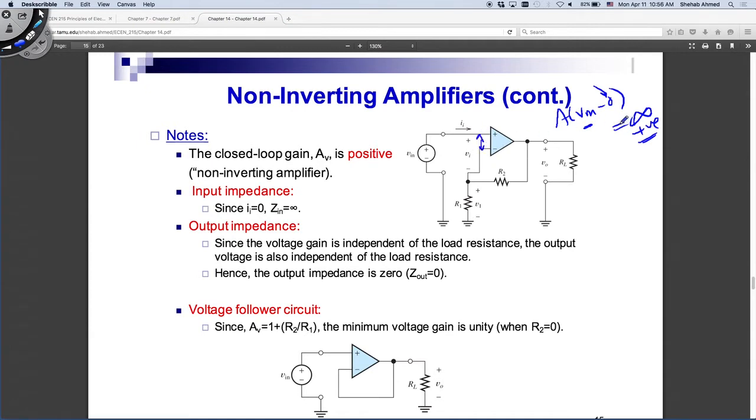If I bring back a negative number, what's going to happen in this case? If I put the resistor here instead of here, what will happen? I'm bringing back a voltage to the negative terminal. The output will be A V input times another circuit in parallel with this. It's a voltage source, and in parallel with it, it has some resistor and some output voltage, right? So the voltage that I'm feeding back is another positive voltage, so it will be A times some Vx minus 0 as well, because this terminal is still connected to ground with 0 volts, right?